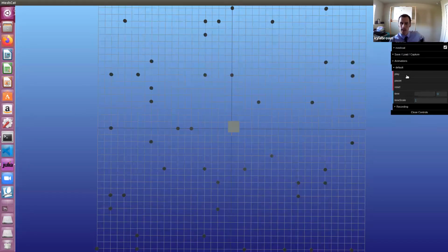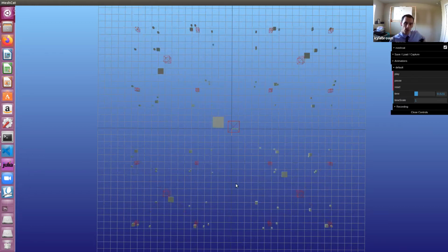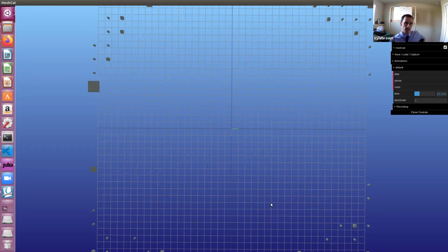So here is a visualization of the same block we just saw, with more robots in the scene, and the collision avoidance is turned off. If you watch closely, you'll see that as the robots move along, they move around the purple circles that represent the staging areas. They always go around them in the clockwise direction if they're on a collision course on the way to their goal.